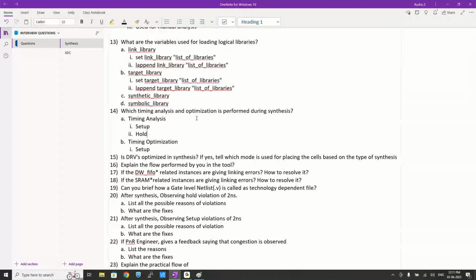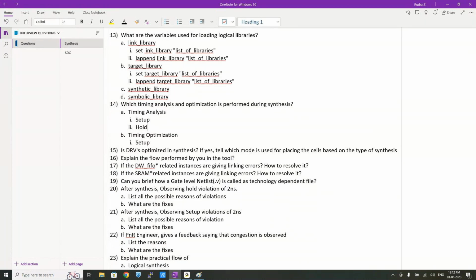Yes, clock pulling has to be done with respect to capture, or clock pushing has to be done with respect to launch. So we are expecting more congestion. Whether that particular path is expected or not, that verification is what we are going to do here. No other cases, only analysis.